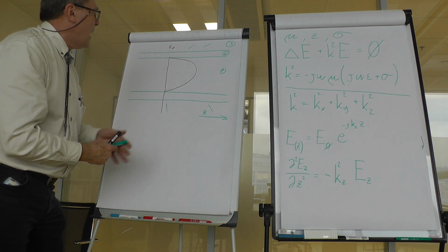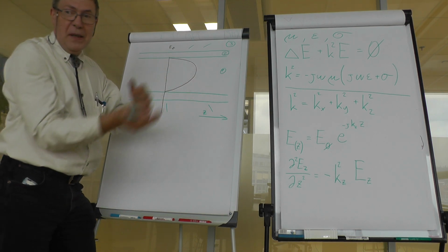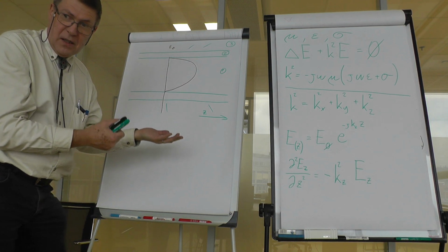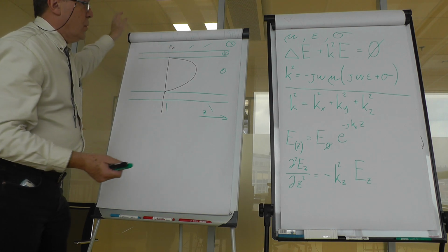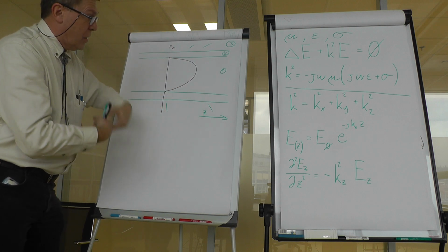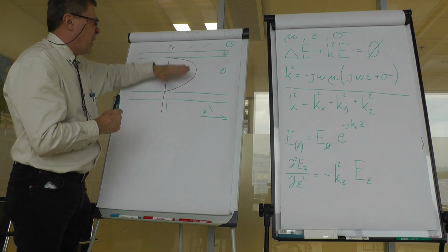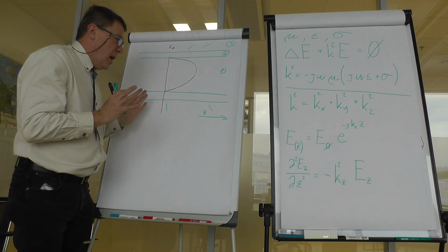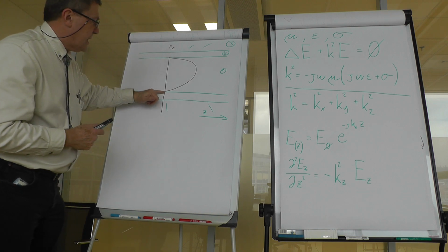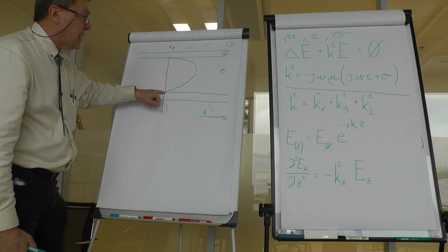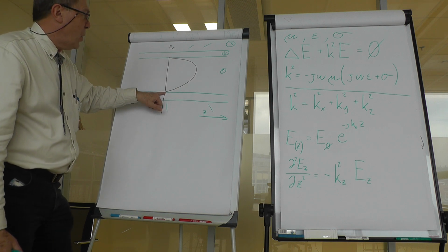Then we will be having this as one half of a sine or cosine, depending on where you choose your coordinate system start, and we will just use that set of equations to generate other components of the field from it. That would be in the case of perfectly conductive walls. We could possibly use it for classic metals, because still the component at the surface of a metal, the tangential component of electric field strength, is quite small.